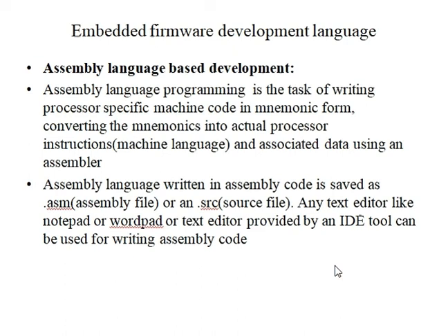Over here we often call it a cross compiler rather than the compiler. So cross compiler because we are using .c file too. If you would have used just assembly code, .asm file or .s file, then it would have been just assembler. Since we are using both languages, it should support your ARM target machine. Hence we need to use a more sophisticated program which should include compiler as well as assembler. Fine, so we write a code first, then we will be using a toolchain, a huge program which has all the methods for converting a given assembly level language into a machine level language.